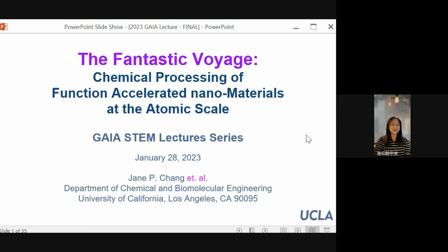Specifically, her research focuses on developing novel atomic layer controlled thermal, radical, and plasma enhanced deposition techniques to synthesize compositionally controlled conforming coatings, either on a planar surface such as a wide band gap semiconductor, or selectively over complex 3D surface topology such as in a 3D micro battery or fuel cells.